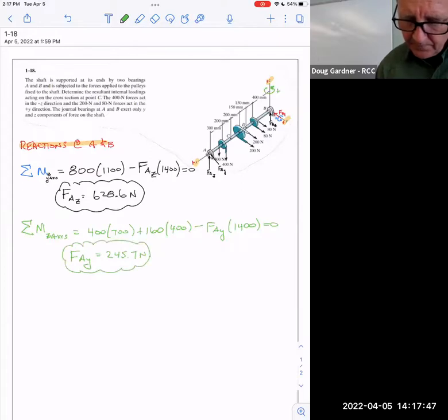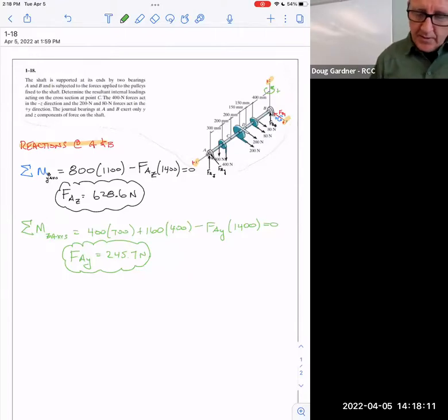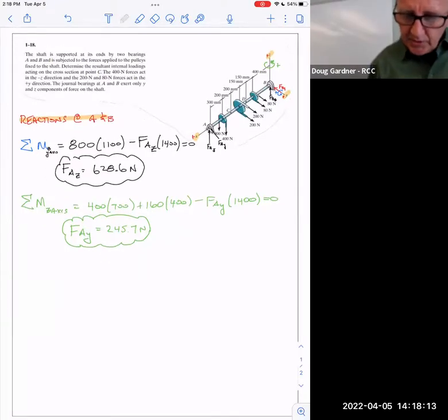So in this specific problem, it doesn't seem like there's any consequences if you were to move that Z and Y axis over to A. Absolutely none. You're exactly right. You could totally move that Y-axis over to A and redo this whole thing. Now, you know, the moments are more trouble. Does it make sense I could now switch to the forces of X, Y, and Z? Because I now have 2 of my 4 unknowns sorted out. And so I can now switch gears to see what's happening on the other side.